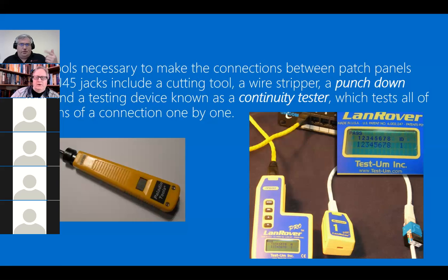So Peter, can I add to that? Well, I've got a lot of experience in that area, and you're right on time. I know that his question with the connectors is that oftentimes when going to the higher frequency and the higher transmission rates, your medium, the type of copper or the number of twists, some of those have got gold contacts in them for the high end, super high frequency stuff because of the conductivity. They don't want any oxidized pins in there to slow down the transmission.